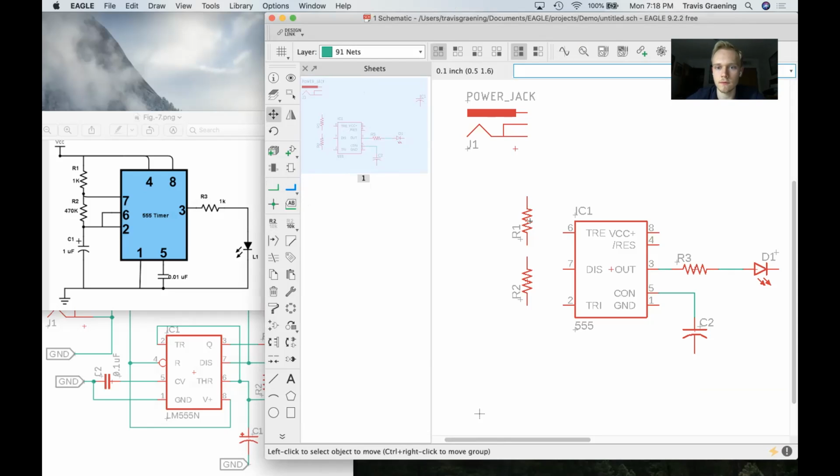So I'm actually going to move this up a little bit. Sure, that should be good. So I'm going to want to connect resistor 7 to resistor 1 and resistor 2. That's not 7. Okay, resistor 1 will have to be connected to 7 and 2. Net here. And right there. So I've connected both of those. As Jackie mentioned before, you can see that this little green dot has appeared, which means that all of those are connected together. And if I want to move things around, you can also move traces like this.